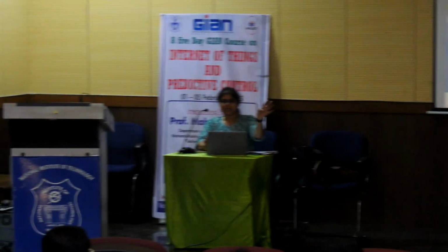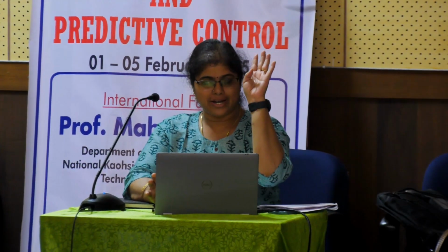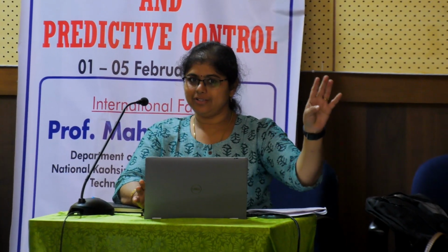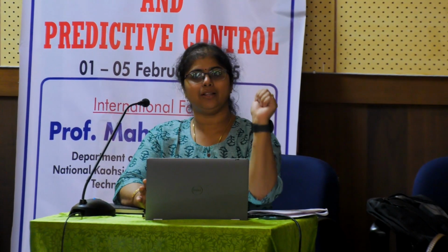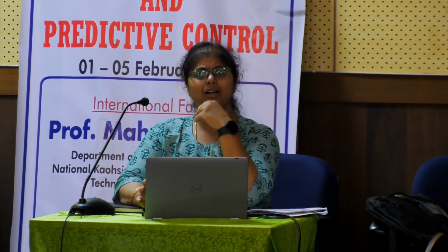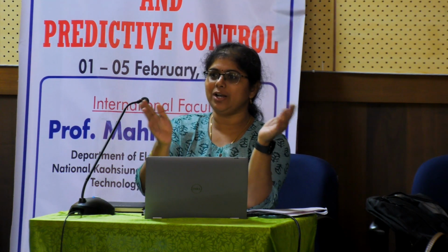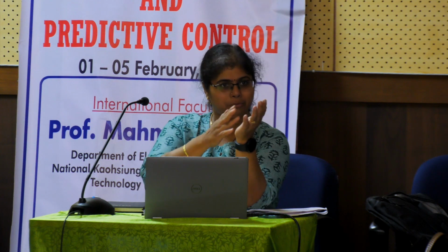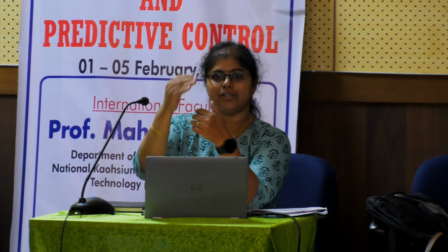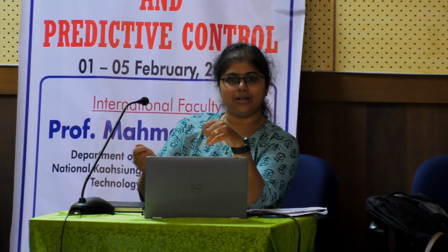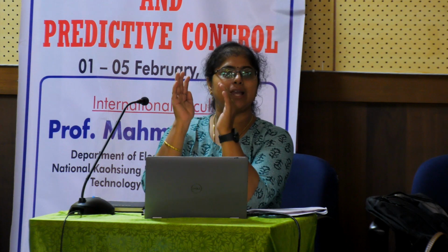So, 3 things are important in MPC controller design: the plant, setting the constraints, getting a generated reference signal that you want to control, then designing the controller. That's all. And designing the controller is very simple. You have to just type MPC designer. Once the design window comes, you have to just give the IO attributes, input output attributes. Check whether my model is linear or non-linear. If it is non-linear, then I have to again go and change the step size, make it linearized. What is most important is designing the plant.